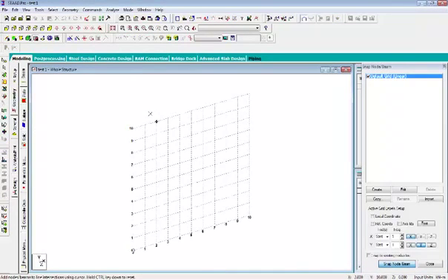One thing about file naming, I would say never name a file as structure1, because by default the name is structure1, and if you save a file, do some work on structure1, and again go on doing it as structure1, the previous file will be replaced by the new one. So all the work you have done will be of no use at the end.